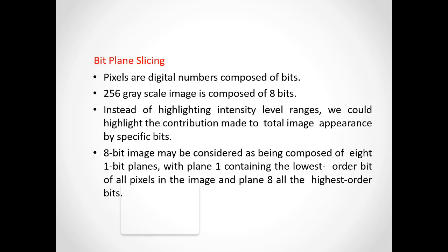significant bit. The higher order bits, especially the top 4 bits, contain the majority of visually significant data compared with the other bits. So, the top 4 bits will have more data with respect to the image compared to the lower bits of the image. Separating a digital image into its bit planes is useful for analyzing the relative importance played by each bit. Also, this method is useful and used in image compression.